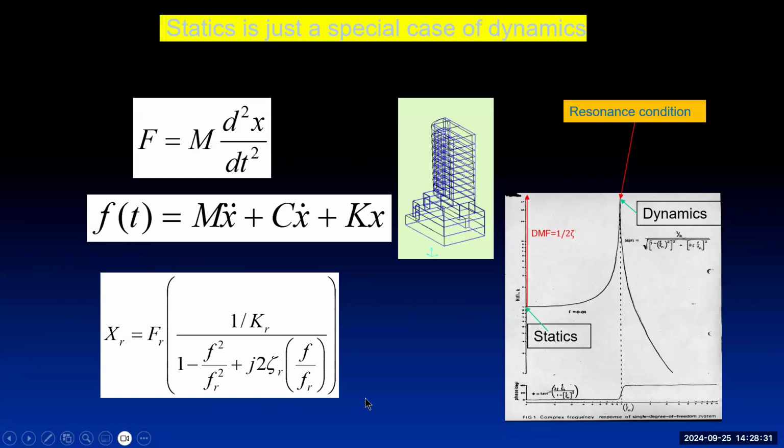We have static or dynamic. So in other words, we can have displacement is the force times some mathematical function, which is a representation of the structure. The force action has two parts here. We have statics, which occurs ostensibly at zero frequency. Nothing occurs at zero frequency, so we assume that it does, and we get approximations to the static response. And then we have the dynamic response, which is a resonance condition of a structure. There is a multiplication factor if the structure is behaving in its resonance condition.